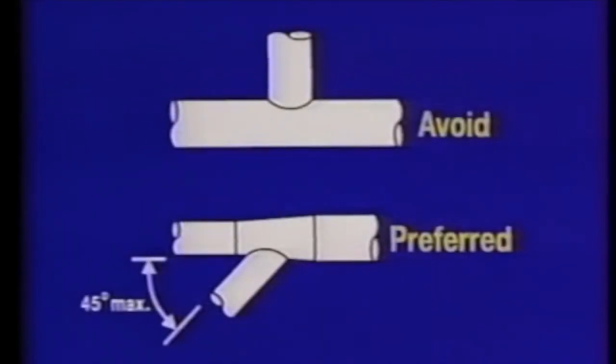Be sure to maintain an adequate transport velocity in the duct, or the duct may fill up with dust. An alternative is to provide clean-out openings at intervals throughout the ductwork. This, of course, increases maintenance requirements. Avoid 90-degree T's in the ductwork. Turbulence resulting from changes in air velocity and direction causes pressure losses in the system, which must be overcome by the fan. Branches should enter at gradual expansions, at angles of 45 degrees or less, to maintain duct velocities while minimizing turbulence.